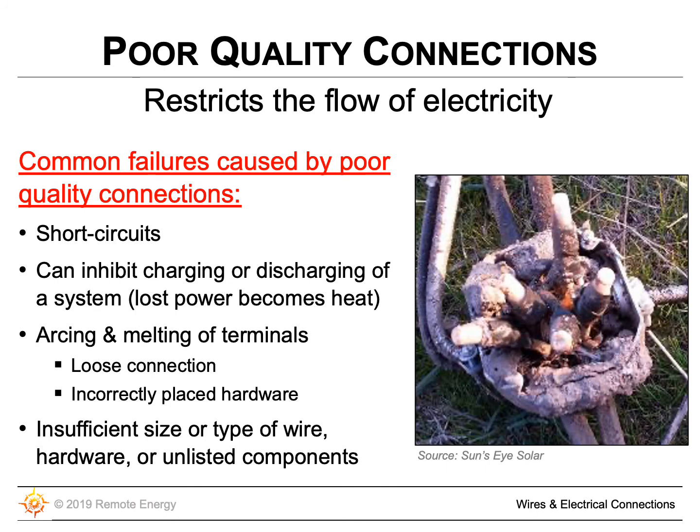So we've run our wire. Now we need to make connections on each side of that wire that are in really good shape. So we're going to make sure that we use some kind of approved method to make sure those wires are connected. What we don't want to do is make a poor connection that could over time build up a lot of resistance. If you have a loose wire or one that potentially could arc, that could cause big problems in the future for that system.